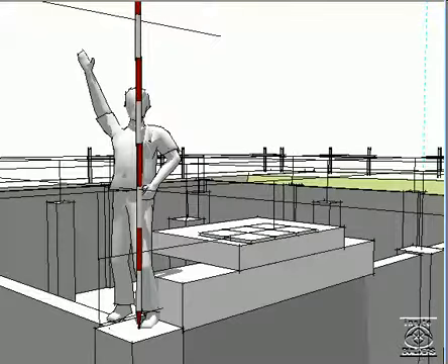So if the finished floor tile is say 1 inch thick, the floor slab is 8 inches thick, and the depth of the beam is 14 inches below the bottom of the slab, that would mean the bottom of the beam, which equals the top of the form, needs to be about 5 inches below the reference point.